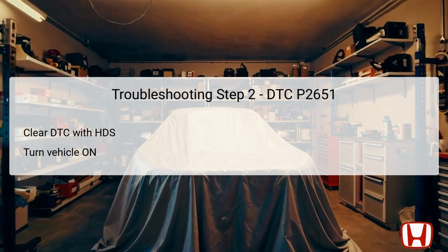If the HDS shows a normal indication, this suggests the system is functioning properly at that time, making it necessary to check for poor connections or loose terminals as potential intermittent issues. This step lays the groundwork for determining if the initial DTC was a one-time occurrence or part of a larger problem. Step 3 entails evaluating the possible failure area by looking at the rocker arm oil pressure switch itself.